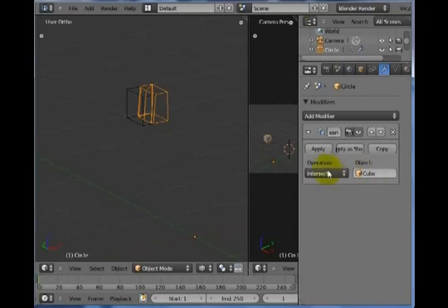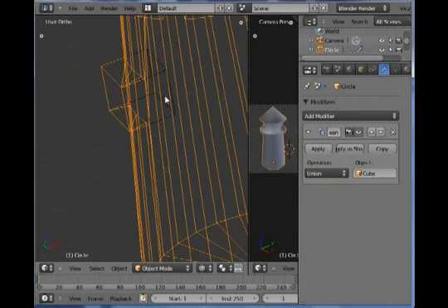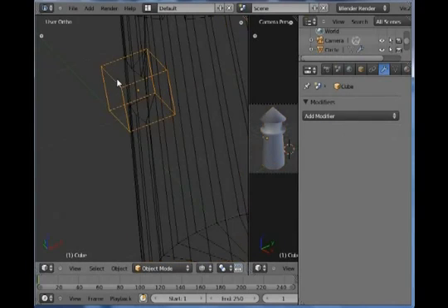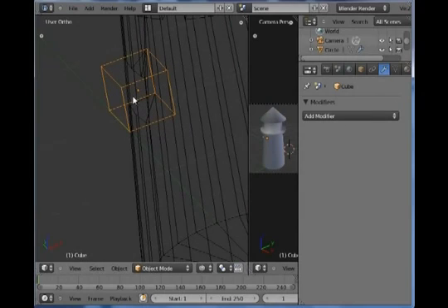I'm going to change it from intersection to difference. And when you look at it now, it's actually cutting a hole out for that. If I go to union, it'll make a new object and it'll join that onto it, and it'll get rid of all unnecessary faces and vertices. Well, I want to go difference. And this is going to be live, meaning I could grab the cube, and as I move the cube, the lighthouse will update until if I pull the cube out of there, there won't be a hole anymore. It's a live setting.